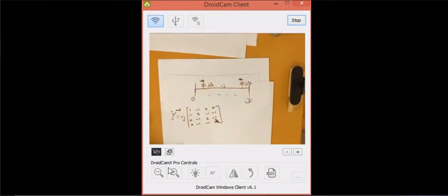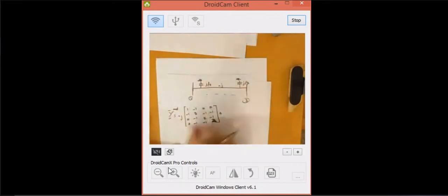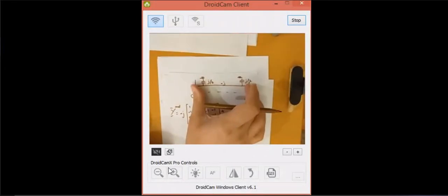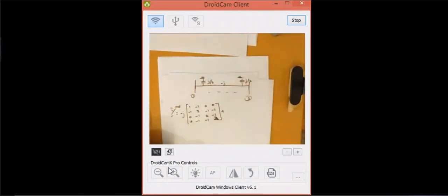Okay, so you can do it in one step, or you can do it in steps. In one step, it means that we add this one, this line. Then the second we add this, the third we add this one. Or you can take this line and find the Y matrix of this and add it directly. So addition of this one means that we add minus y.